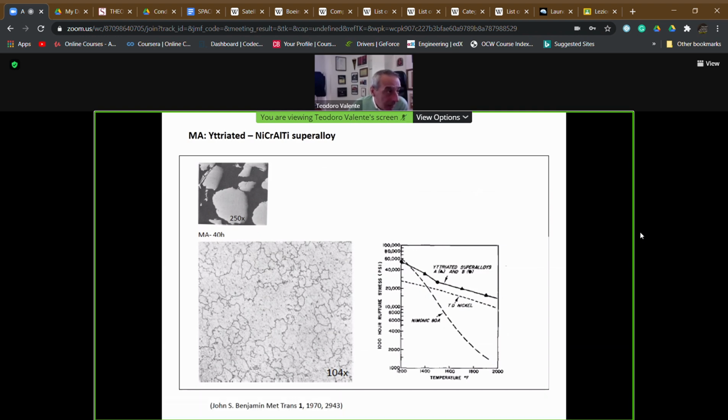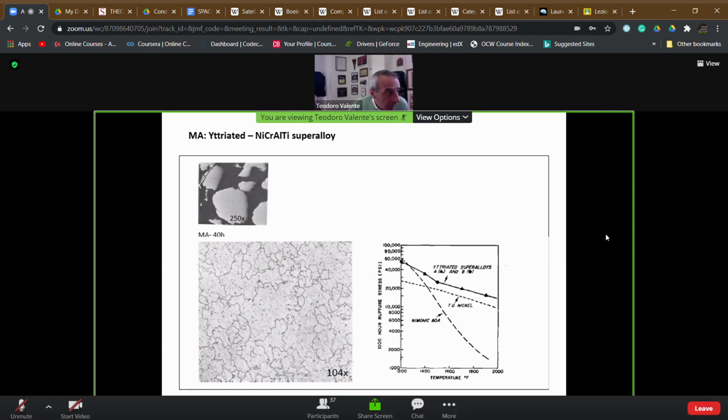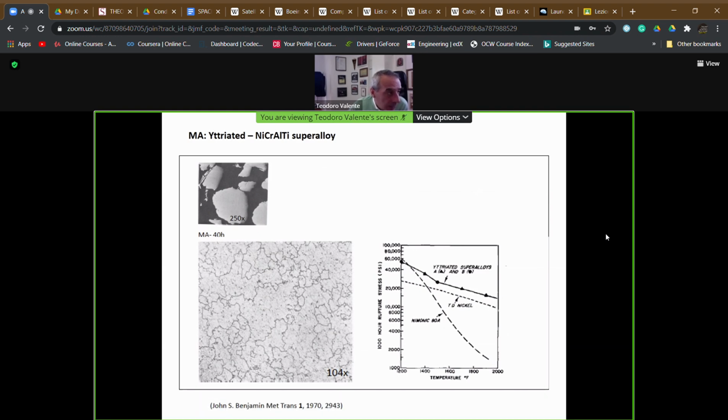We can remember that dislocation movements are made slower because if a dislocation meets a non-metallic phase, it cannot move inside it, but must activate the climb or cross-slip mechanism, depending on the dislocation type, in order to travel around these obstacles.